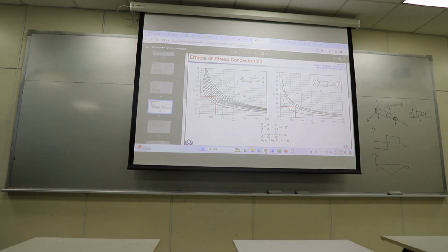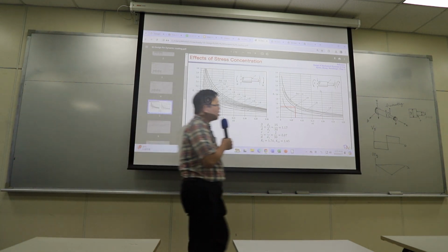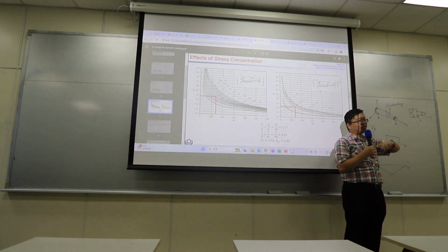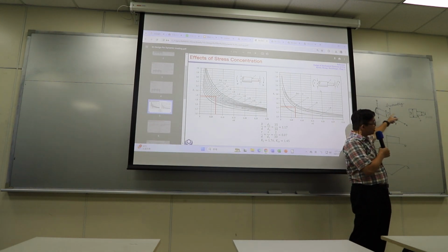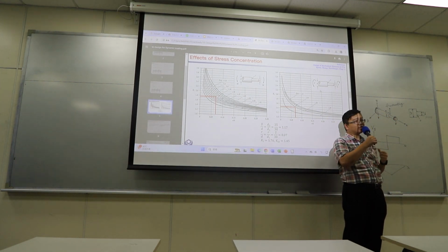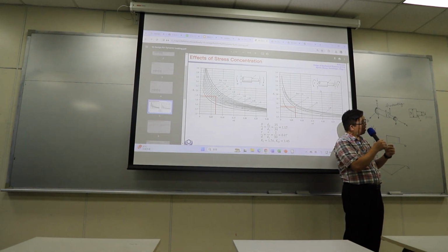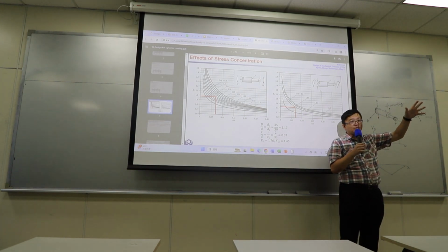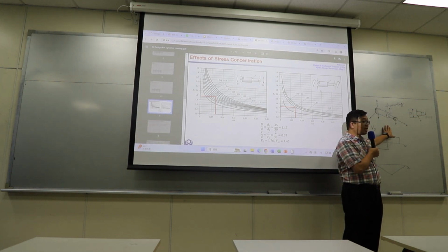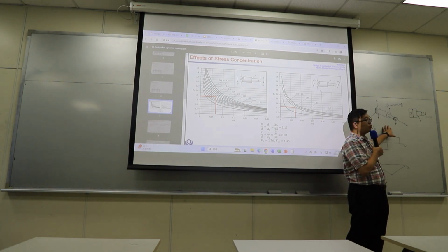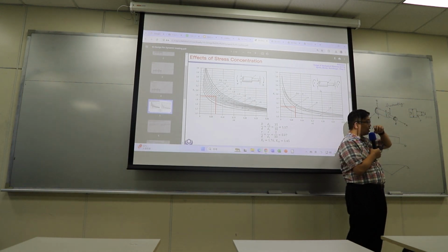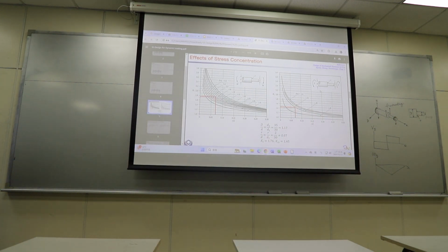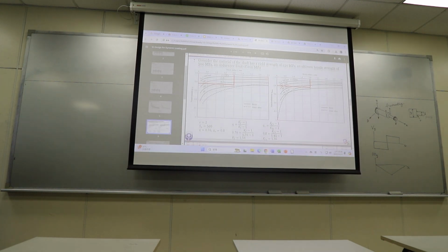And then, because the problem will tell you this shaft probably is moving in a way such as rotating, or maybe the tension in the belt is changing its amplitude with time, fluctuating. So for tomorrow's problem, there will be dynamic loading for the shaft. So you need to worry about fatigue. Then you need to use a different set of figures like these.